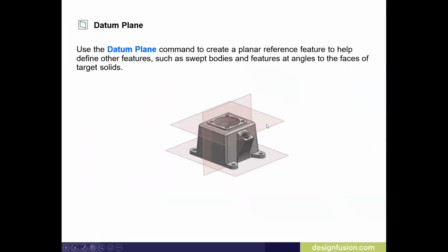All right. So the next thing we'll talk about is creating datum planes. When you're creating planes, sometimes you need to create either an extrude, or just what I just showed you on the previous one. You need to create a plane that's out somewhere, not always normal to that part. Sometimes you need to start creating these planes to get different orientations to create a new feature, things like that.